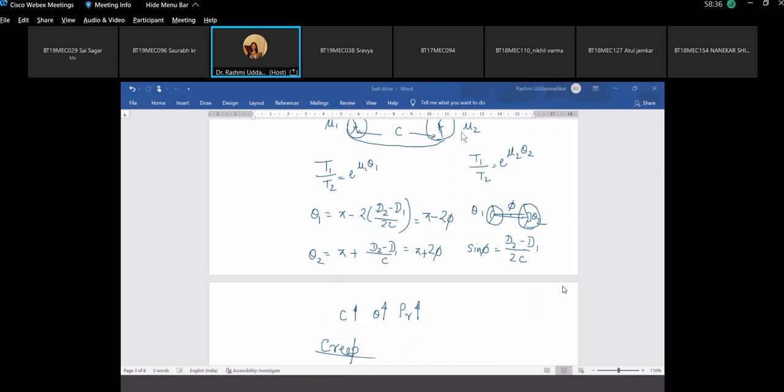Again it is stretched and it is compressed. In between the two pulleys, it has its normal length. This alternate compression and extension of the belt leads to change in its modulus of elasticity, and ultimately it leads to failure. So creep in belt is due to continuous extension and compression of the belt.